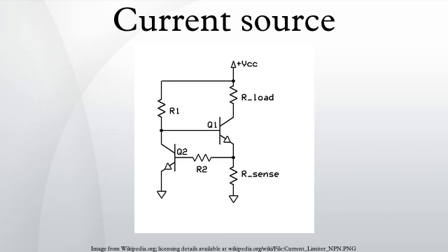Also, a current source should not be connected to another current source if their currents differ, but this arrangement is frequently used. Similarly, an ideal voltage source cannot be connected to an ideal short circuit, since this would result in a similar paradox of finite non-zero voltage across an element with defined zero voltage. Also, a voltage source should not be connected to another voltage source if their voltages differ, but again this arrangement is frequently used.